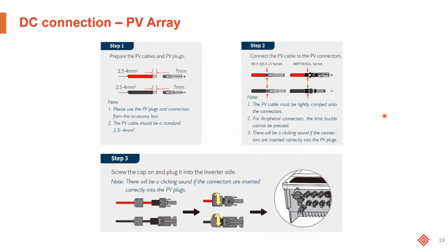This is important because there is an IEC standard on crimping the pins onto the cable. So there is a particular profile and there is a particular amount of force that needs to be applied onto the cable to ensure that the crimping meets the IEC standard. So, very useful to know.